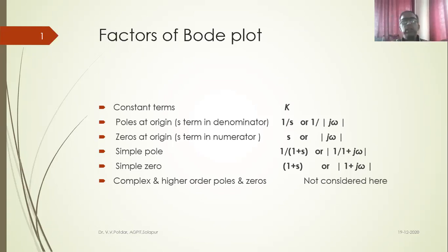If you cross the limiting value of K, steady state gain value K, beyond this value, the system will tend to become unstable. So this is the benefit of all these frequency response plots and pole zero plots. We can get to know about the system performance characteristics and we can improve upon the system behavior.